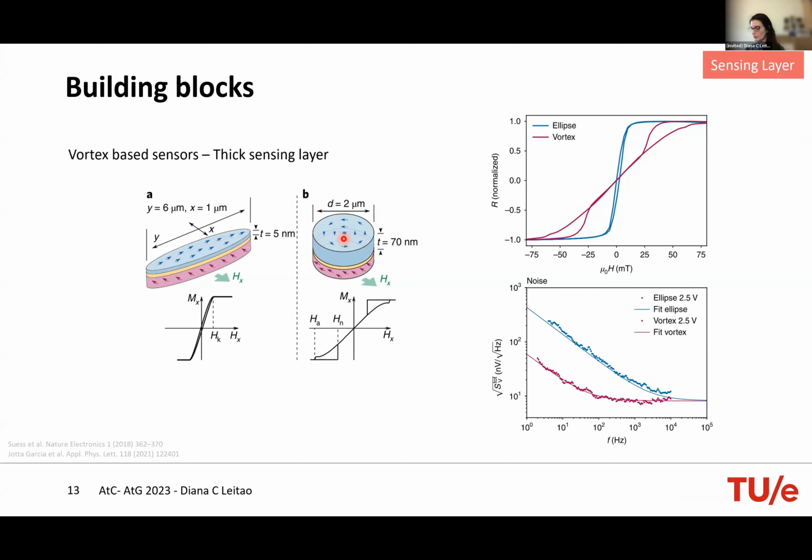Typically here, I think they are mostly nickel iron based. Also the shape. You need to ensure that you pattern a round shape to be able to accommodate the vortex. And another quite important trick in these devices is that when defining the free layer, we need to ensure that we stop very well at the barrier or the spacer to define this quite circular area in the free layer part.